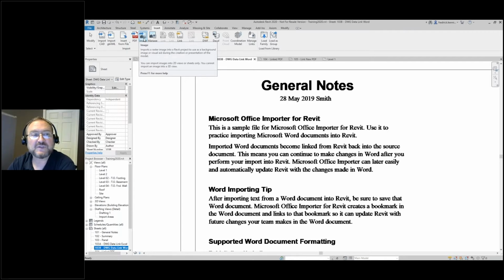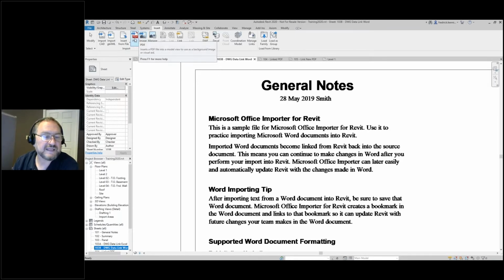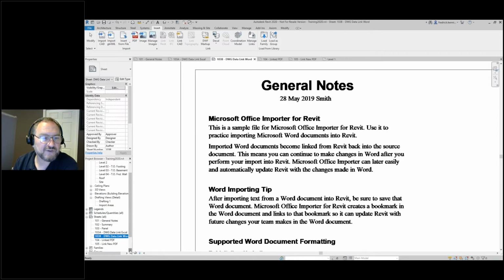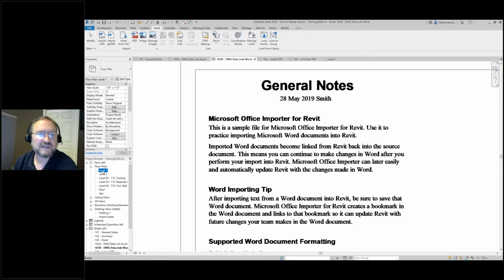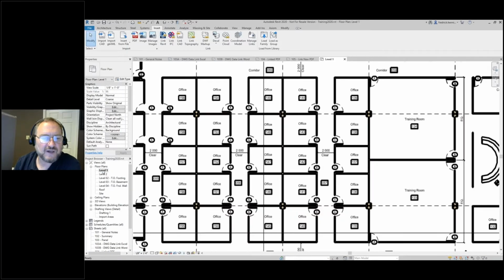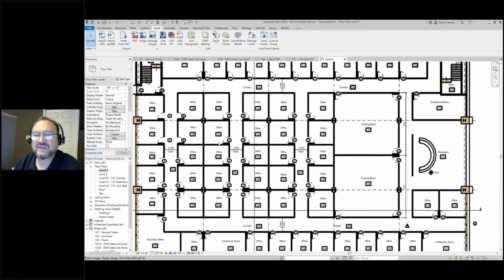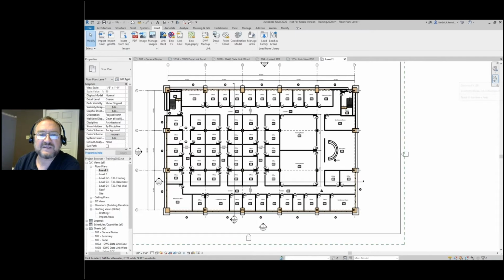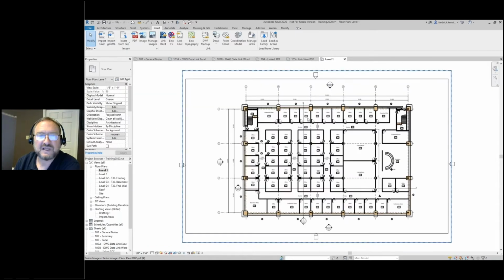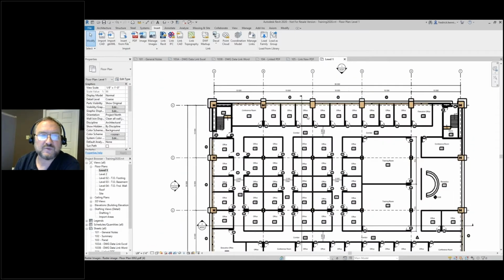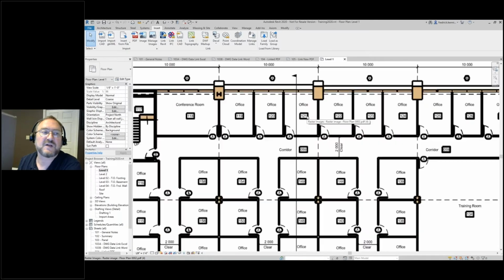But in this particular version, you can use this PDF, link PDF or insert PDF, and you'll get instances like this. For example, in floor plans, what I did is I took an AutoCAD file and I saved it out as a PDF, and then I linked the PDF using that particular option. And when I zoom in, the resolution of the printout I did from AutoCAD was, I think, just 300 DPI or PPI.